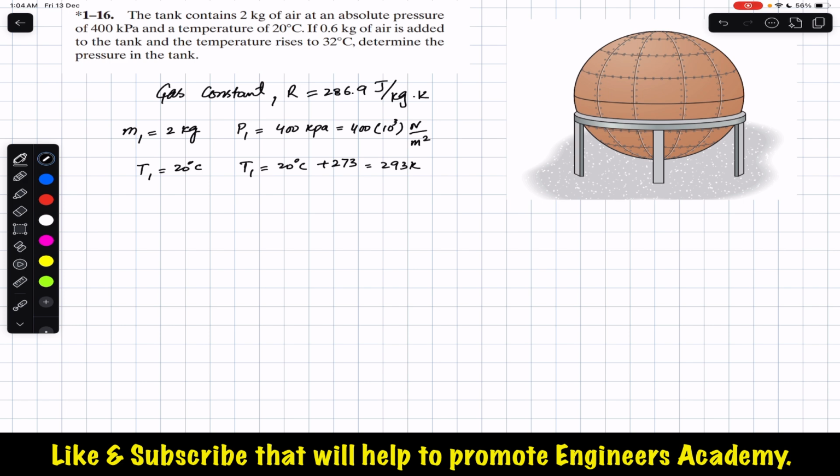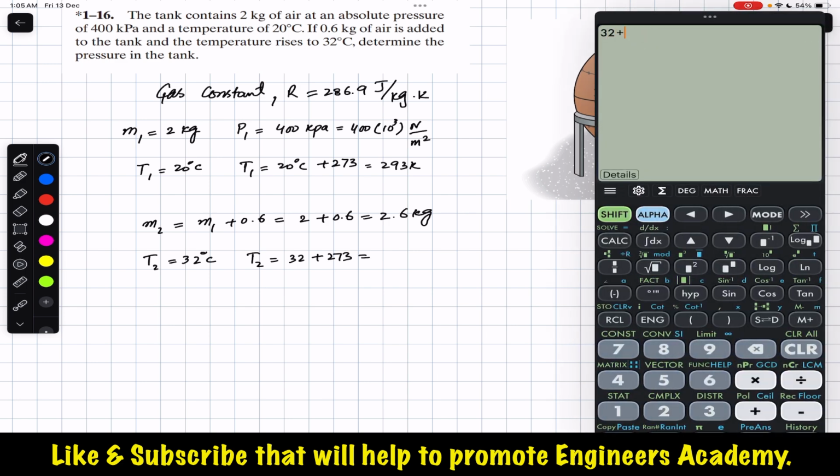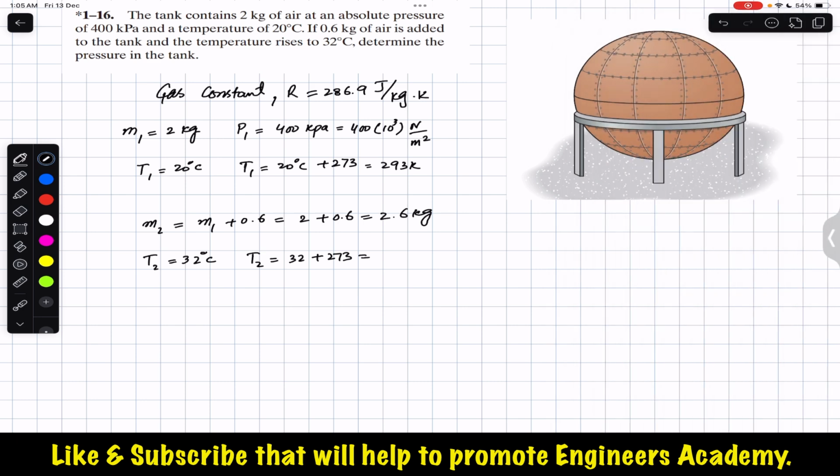Now the problem says that if 0.6 kg of air is added to the tank, so this means that mass 2 is equal to the initial mass plus 0.6. So initial mass is M1, which is 2, plus 0.6, this is 2.6 kgs. So the temperature rises to 32 degrees C. So T2 is 32 degrees C, which in Kelvin is equal to 32 plus 273. So 32 plus 273 is 305 Kelvin. So we are asked to find P2.